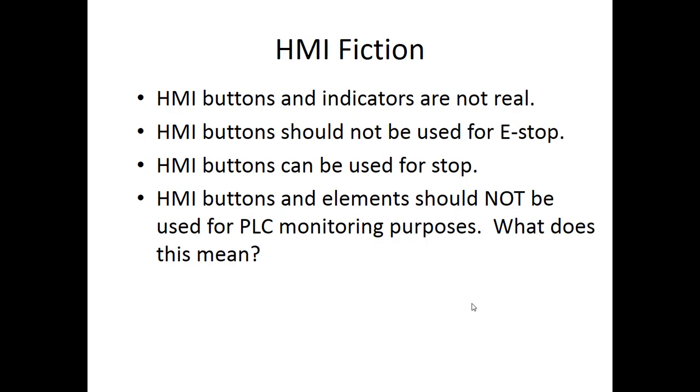HMI buttons and elements should not be used for PLC monitoring purposes. Well, what does that actually mean? Well, they are used, like I said, with bingo boards and stuff like that. So it is nice to see what is going on with the PLC, but you have to be aware that there is some lag time between the HMI buttons and elements and what you're seeing on the screen. Okay, it's not instantaneous.